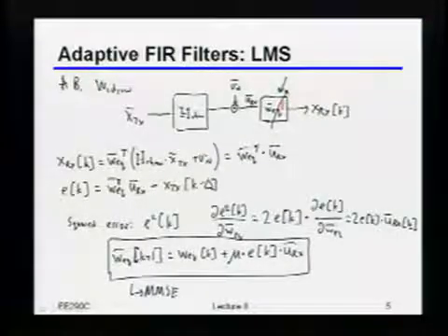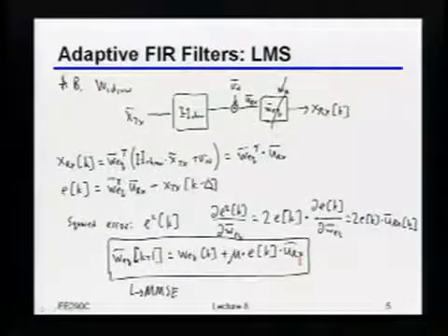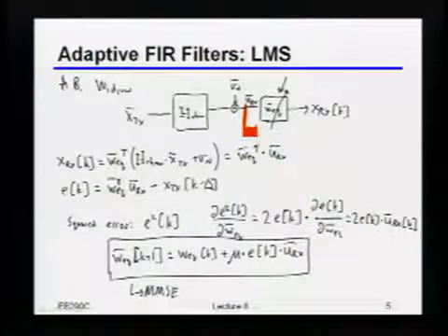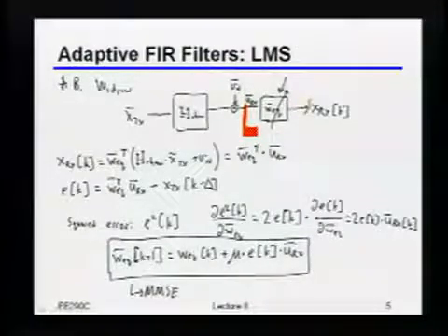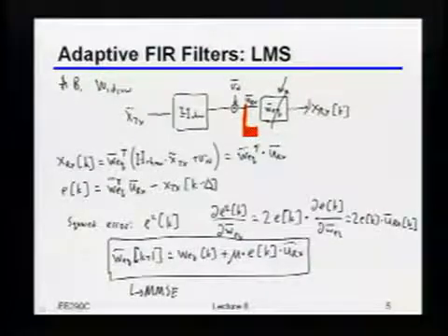If I'm making the right decisions, then I do know what my own data should be, right? Now, by the way, in this particular algorithm, if I really do it this way, notice I don't actually have to know what the data is. I just have to tap off at this point and measure the correlation between that and my received analog signal, right? So I don't even have to explicitly know what the transmit bits were. I just have to measure the correlation between the input of the equalizer and the output of the equalizer.